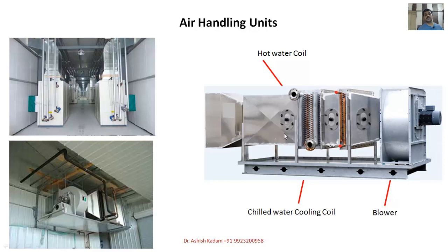Even the AHU has to be made out of the right quality of material. You can see this picture, this entire AHU has been constructed out of stainless steel. All the parts of the air handling unit should be accessible for continuous observation, so that you can keep these areas clean, free of insects or germs, or of filters or coils getting clogged by dust, which then impacts the air circulation even in the growing areas.